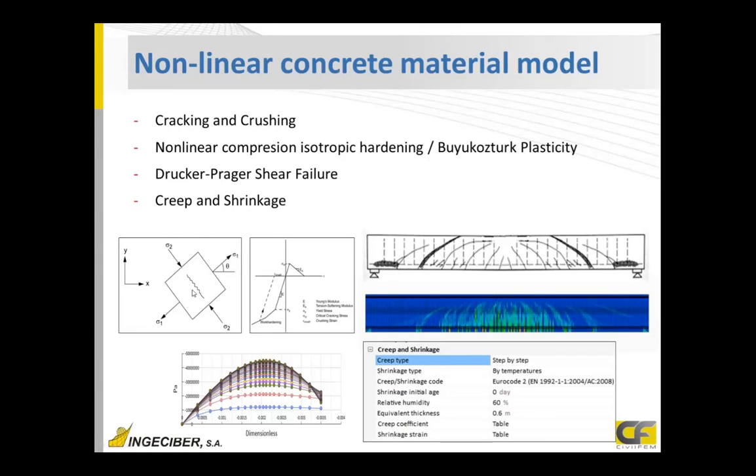For the principal stress, when we have tension and the tension reaches the cracking tension, there's a softening modulus that is defined by the user, where the stresses are being reduced and the strains are being increased. CivilFEM just adds these strains after cracking as crack strains. We can plot those crack strains, and you can see in this beam model these cracks due to the shear effects on the supports and to the bending in the bottom, very similar to the theoretical part.